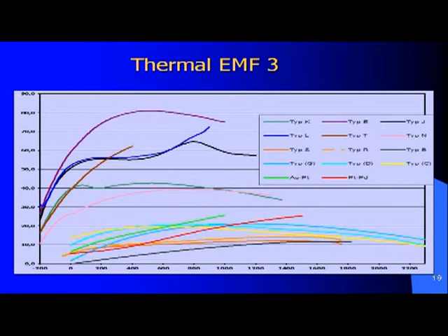And in our previous calibration laboratory, we did about 4,000 calibrations per year, mostly non-noble metal thermocouples. And when you calibrate and you look at the behavior of a thermocouple over time, you have the experience, you look at it and say, okay, this is Tempsens material, this is Isomil material, this is ABB material.